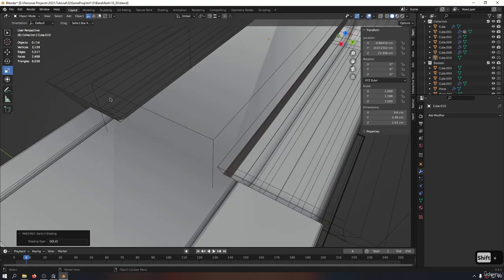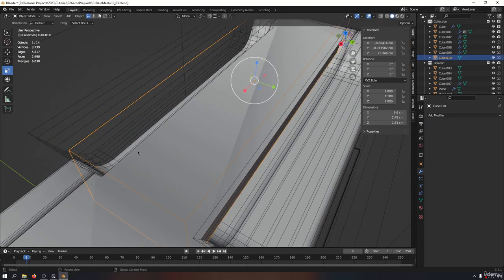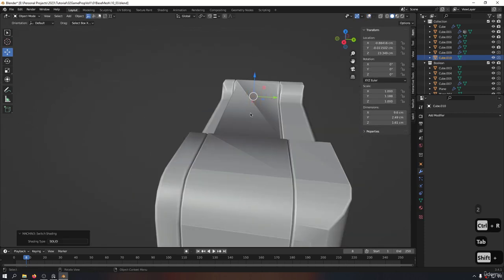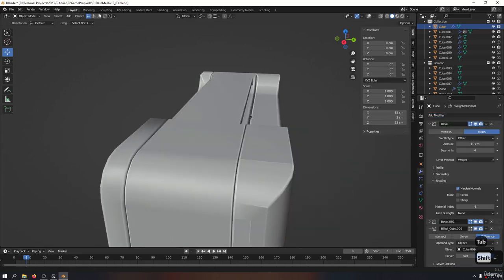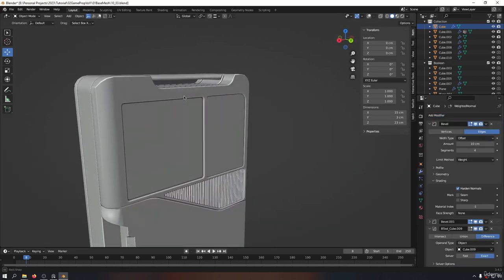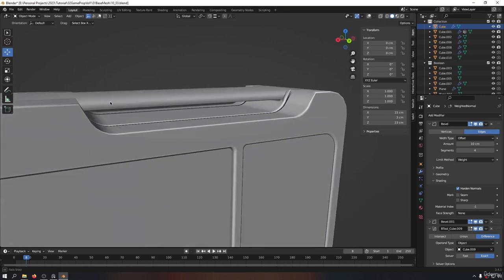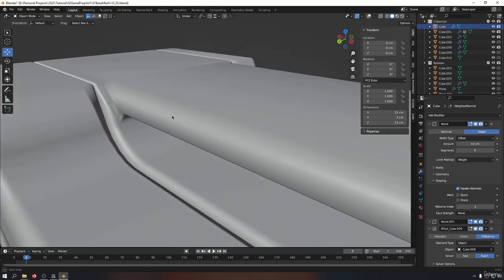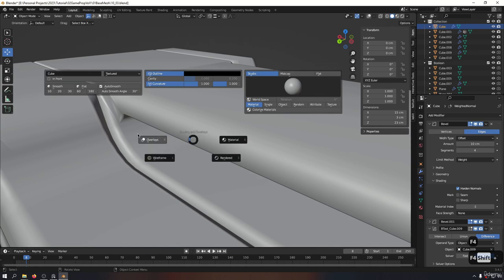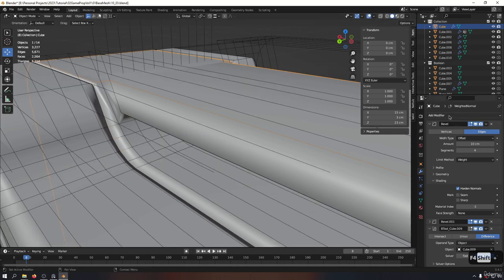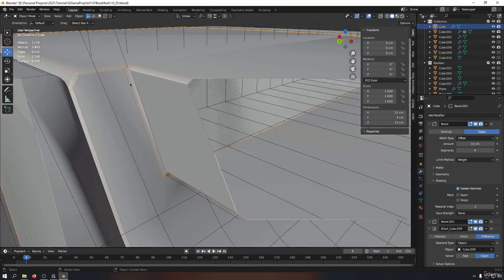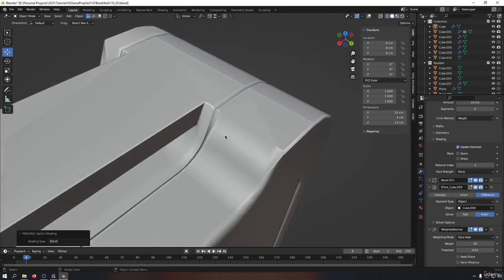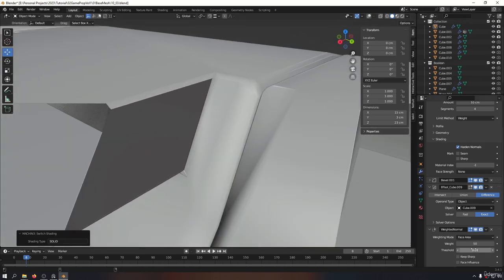And in order to make it a bit better in the shading, I'm going to add some vertices to make the shading all right, and weighted normals to solve the shading issues. Okay, now in here you see using the Boolean or Boolean the bool, we're able to create something like this. And now this actually happens in the geometry. If I go and try to take this and add a bevel, for example, you see now this one is exactly part of the same thing. It's inheriting the lines in here and it's creating a bevel line in here perfectly.